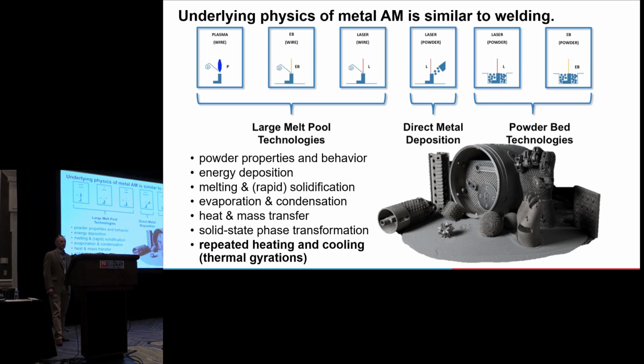There are a number of different technologies ranging from where you blow the powder and hit it with a laser or some power source and melt it as it's being deposited onto something, to where you have a bed of powder and you're hitting it with a laser or electron beam. But all of them have a lot of physics in common: melting and solidification, thermal transport, solid-solid phase transformation, and repeated thermal cycles, sometimes completely melting and resolidifying and sometimes not.